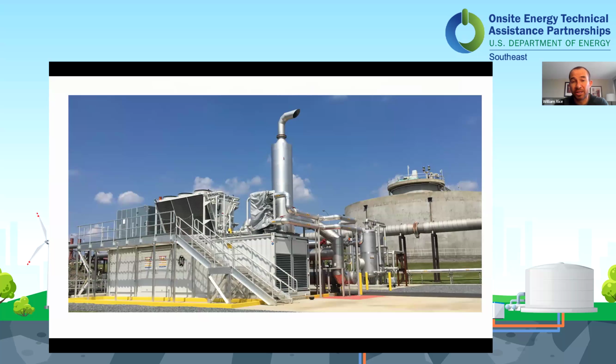This is the final fully completed package. We do have heat recovery, so some of the pipe in the right side of the picture and in the background is part of our heat recovery loop, and we take that heated water and run it to the digester. In the very background are the digesters. That's where we're actually making our gas, and our digesters need to be at about human stomach temperature, right? They're giant human stomachs. So we heat them, they make more gas, and we use that gas to make more hot water to heat them. So we have a nice little feedback loop where the gas production is based on our heat production, which is based on our gas production. A nice little virtuous loop.